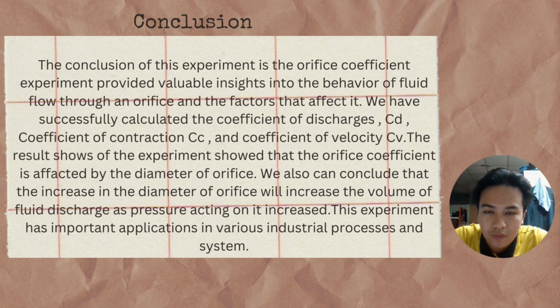So the conclusion of the experiment is that the orifice coefficient experiment provides valuable insight into the behavior of fluid flow through an orifice and the factors that affect it. We have successfully calculated the coefficient of discharge, coefficient of contraction, and coefficient of velocity, as shown on the previous slide. The results of the experiment show that the orifice coefficient is affected by the diameter of the orifice.